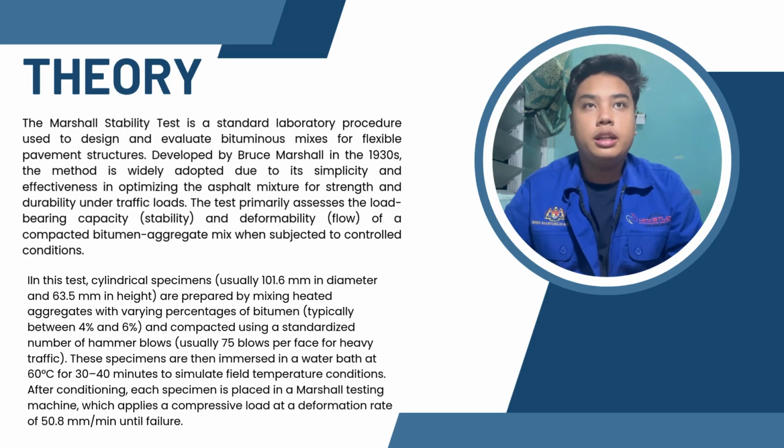The test primarily assesses the load carrying capacity and deformability of a compacted bitumen aggregate mix when subjected to controlled conditions. In this test, cylindrical specimens are prepared by mixing heated aggregate with varying percentages of bitumen and compacted using a standard number of hammer blows, usually around 75.